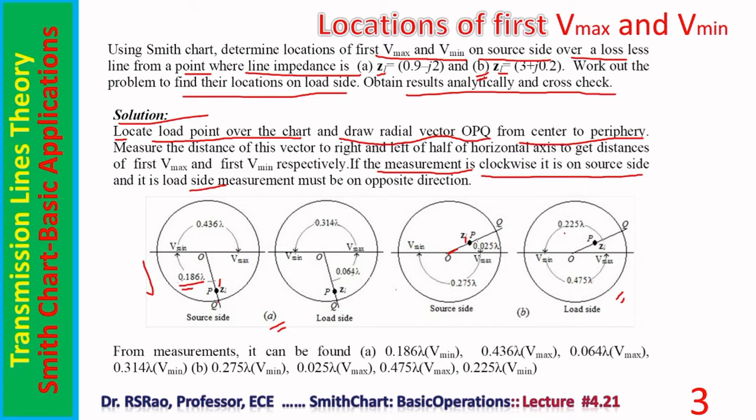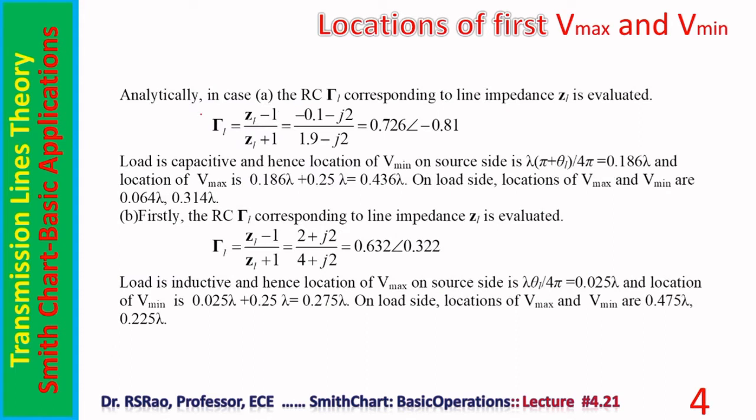V minimum point is at a distance of 0.225 lambda. Maximum point is at a distance of 0.475 lambda. This is load side case. Analytically, also one can do it.